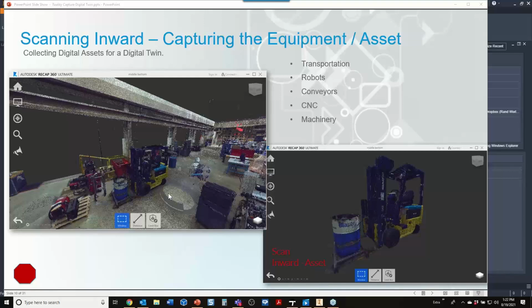A facility is usually a big thing, and in scanning terms, these big things take multiple scans. They typically come together and are stitched together and registered to produce this big thing. And I'm not going to dive into the weeds of registration, okay? But bigger things tend to register together better than small things. It's a function of the scanner. So when you're scanning smaller things, you take that into account. Smaller things, usually you don't scan as many times.